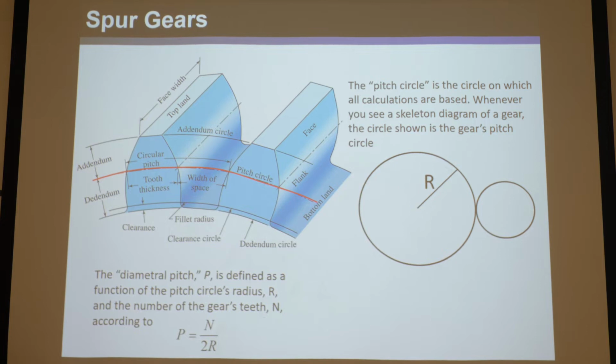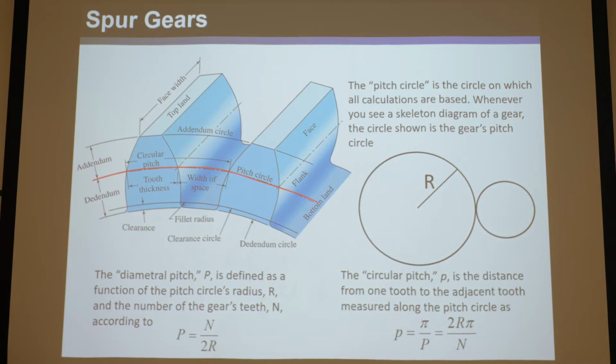So we have this new equation, and this is kind of a characteristic number for a gear, but what does it mean? Well, honestly, it doesn't have much physical meaning, but the circular pitch, small p, italicized, does. So you've got a capital P italicized diametral pitch. You want to memorize that, it's this, and small p italicized is the circular pitch.